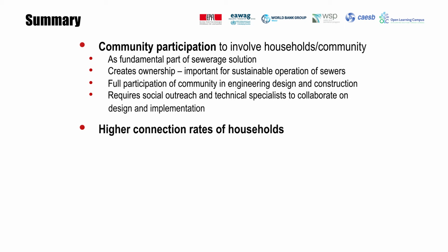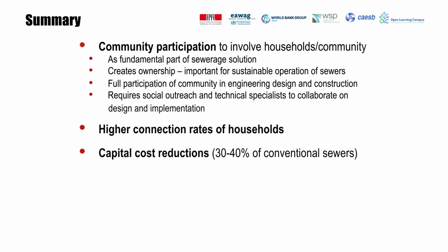This participation throughout the project cycle leads to high levels of connection by households to the sewer network, often reaching 100%. Given the optimization of the local sewer layout, the smaller sewer diameters, the shallower depths, and the greater distances between the inspection chambers, the costs of the condominial sewer civil works can be reduced by some 30 to 40% of the cost of a corresponding conventional sewerage solution.